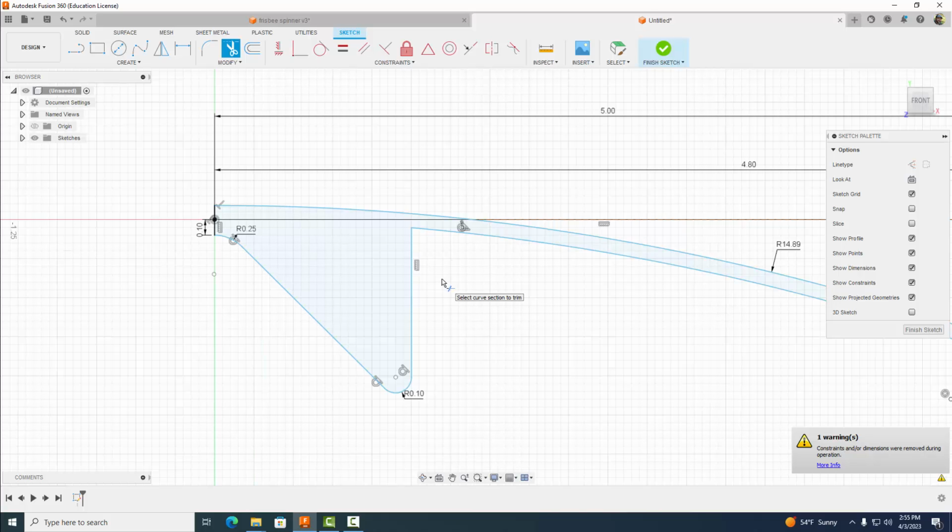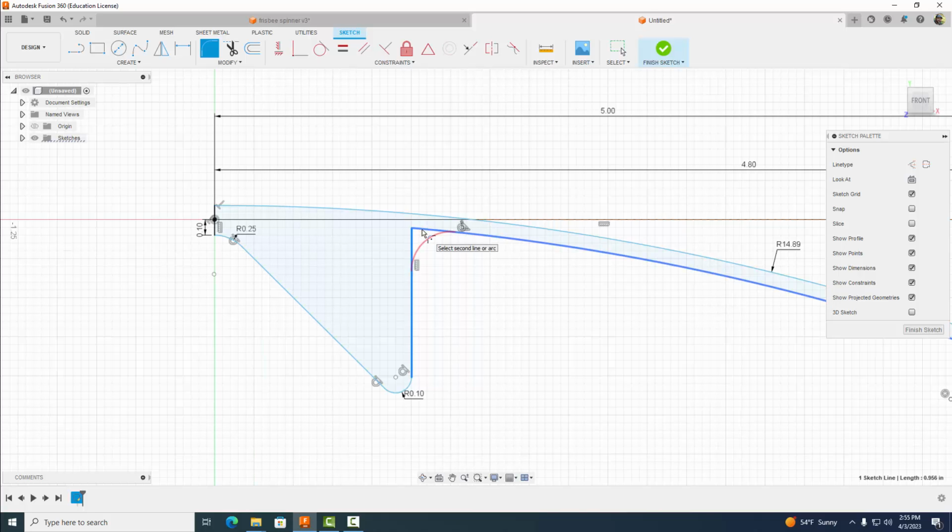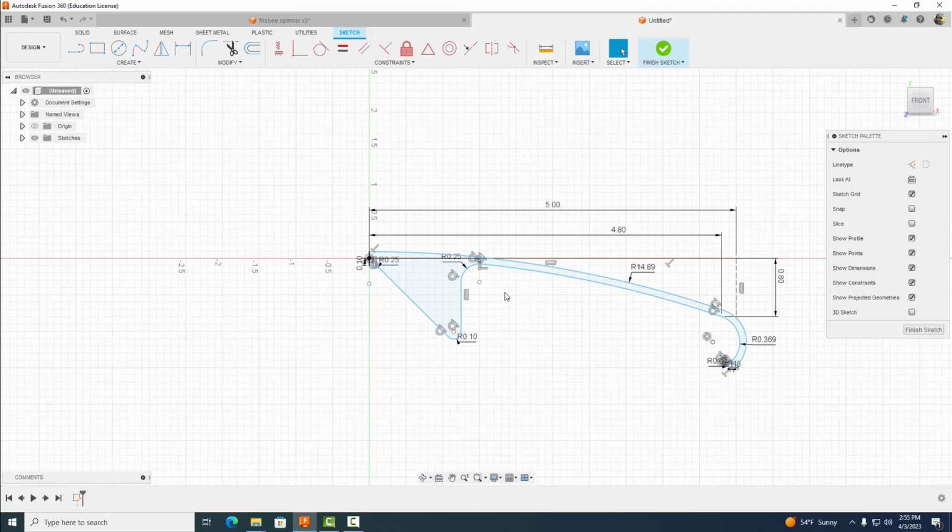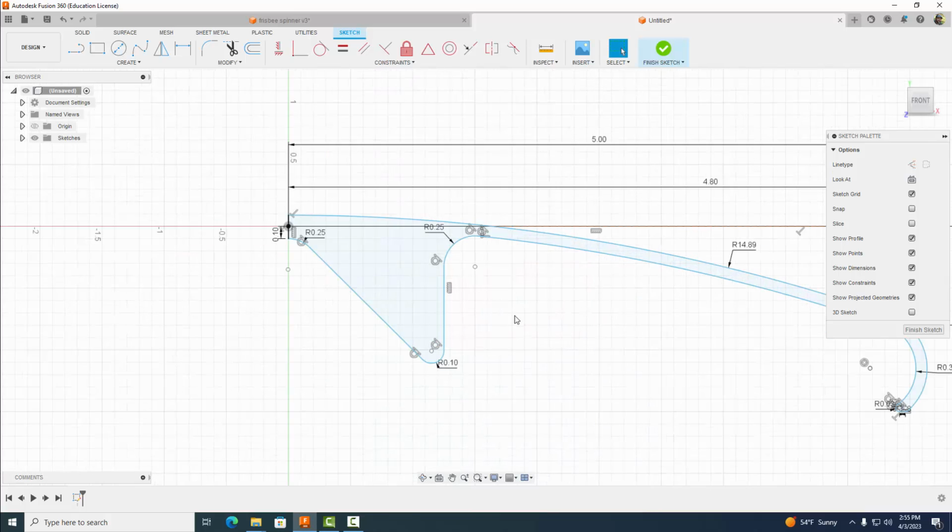All right, and however, I'm going to actually go ahead now and throw another fillet in here, just because if you want to 3D print it, it will probably help create a better 3D print and a stronger 3D print. So I'm going to click there, and we'll set that to 0.25. Hit enter. Okay, when you're all done, you should hopefully have something that looks like this.